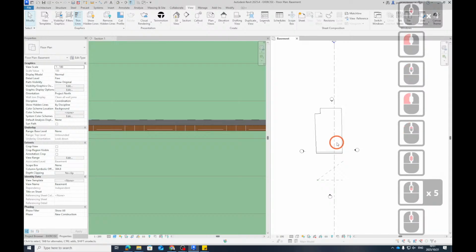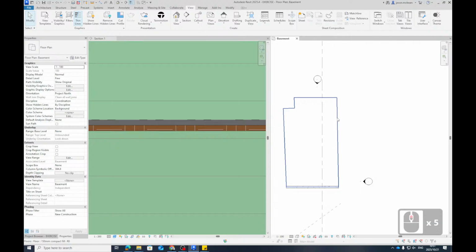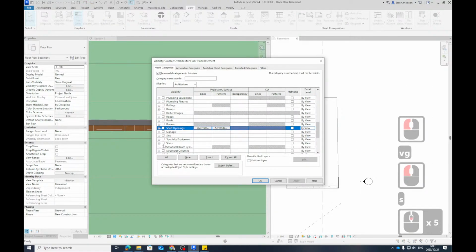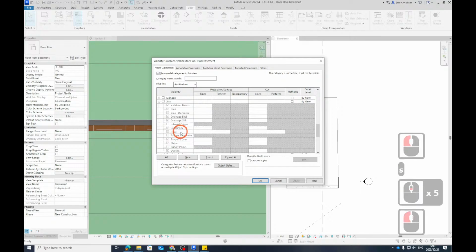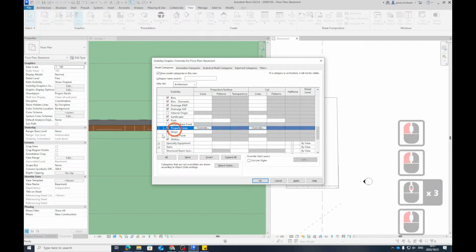When you did your site, did you draw your site boundary? Oh, that is the same one. Let me just double check. That's the long side. There's usually a line that will represent the site boundary. So let me go to site. Let's go to VG, and I'm going to go to Site, because this line is very important: site boundary. This line will have property boundary, property line.